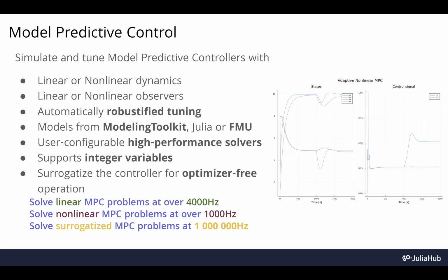At every stage of this model predictive controller, if you're running a control action every 0.1 seconds, each control action is determined by an optimization problem. So the speed of that optimization problem hinges upon whether you use a linear or a nonlinear predictive model within your model predictive controller.